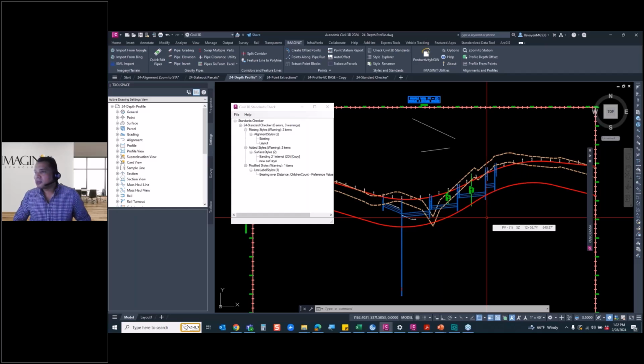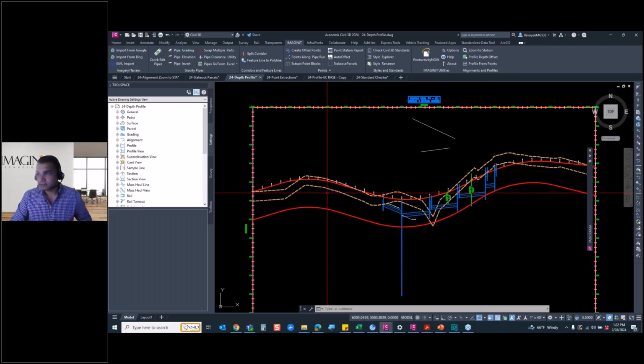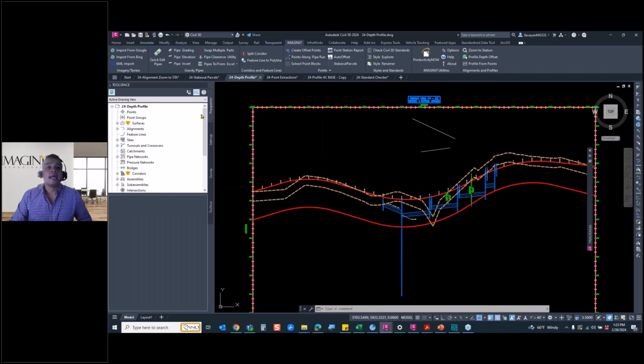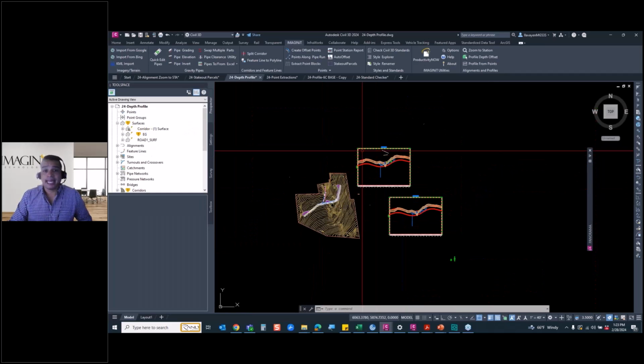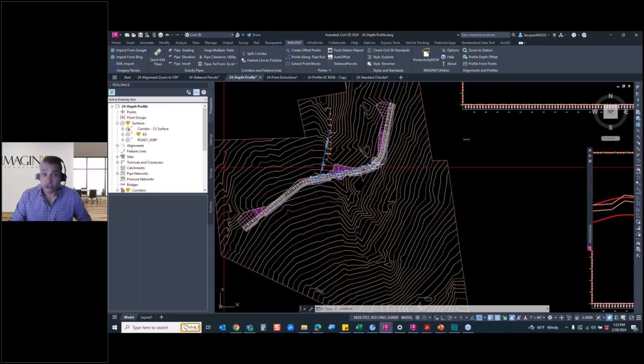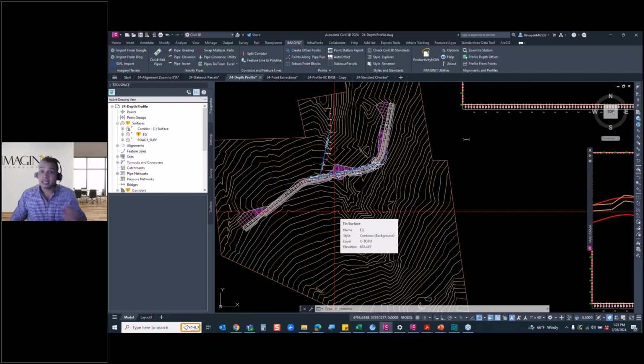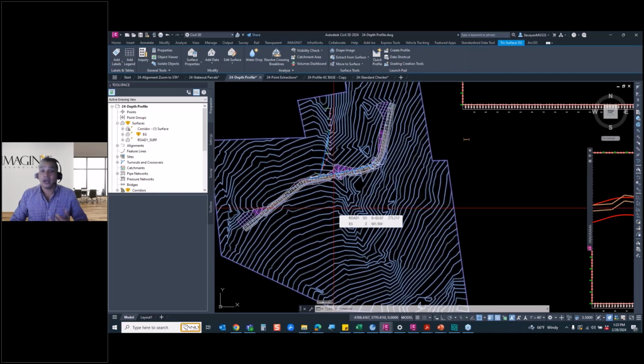Oh, here's another one. A better solution is to make a new drop surface, paste your proposed surface into it, and then lower the drop surface and it will be dynamic. That is correct. You are able to create a copy of a surface, sample that, and have that surface be dropped. The problem with that, or the thing to safeguard around, is how big is that surface? As you copy that surface, you're duplicating the data inside your drawing, and it could be making your drawing a bit heavier as far as drawing size and performance. But that would keep a more dynamic behavior, Mr. Randall. That would work to keep an existing ground looking that way at least. Yes, sir.